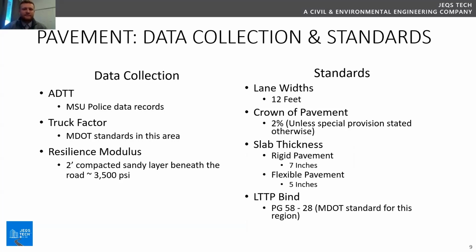To start off, Michigan State University was kind enough to let us make use of their traffic data in order to find the average daily traffic for ESAL calculations. Soil boring logs throughout MSU's campus allowed me to generate resilient moduli. Due to there being a 2-foot compacted sand layer in most areas, a resilient modulus of 3,500 psi will be used.